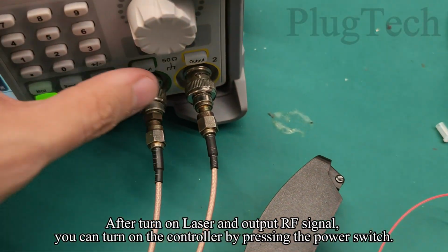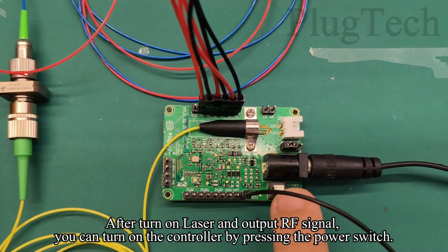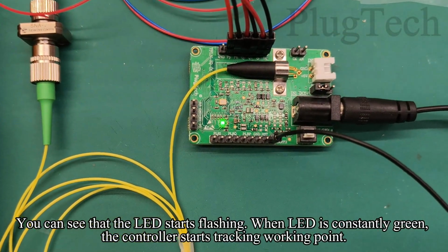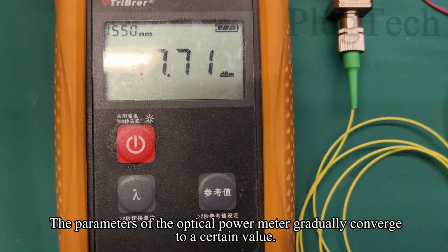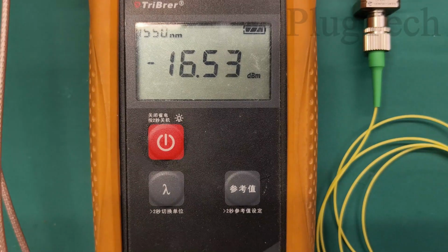After turning on the laser and outputting the RF signal, you can turn on the controller by pressing the power switch. You can see that the LED starts flashing. When the LED is constantly green, the controller starts tracking working points. The parameters of the optical power meter gradually converge to a certain value.